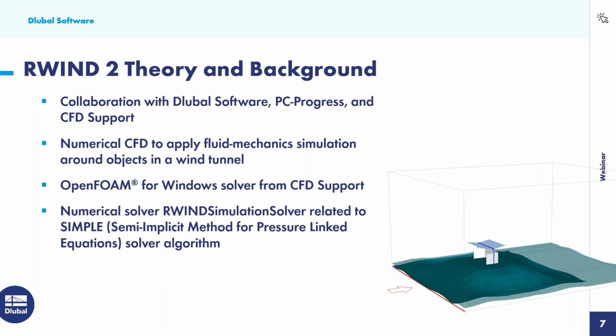It does utilize the OpenFOAM for Windows solver that was developed by CFD Support. It also utilizes the numerical solver RWIND simulation solver, which is related to the SIMPLE solver algorithm, and SIMPLE stands for the semi-implicit method for pressure-linked equations.